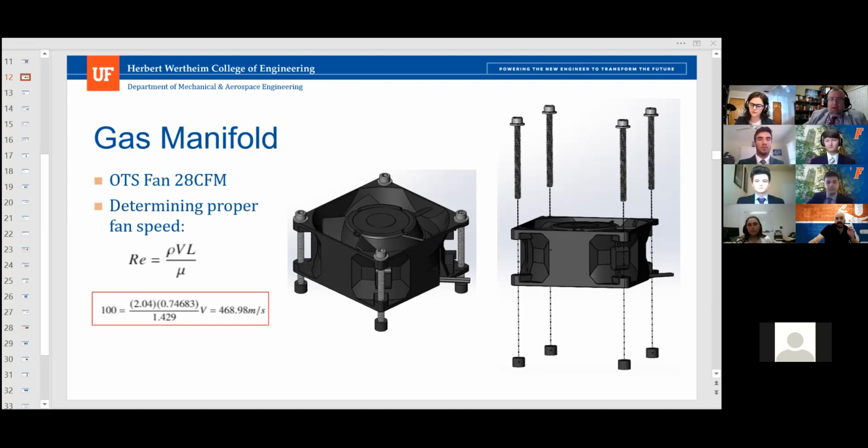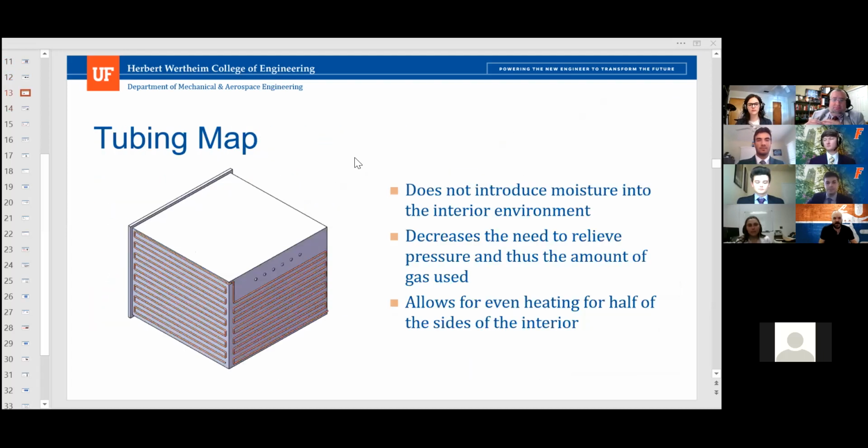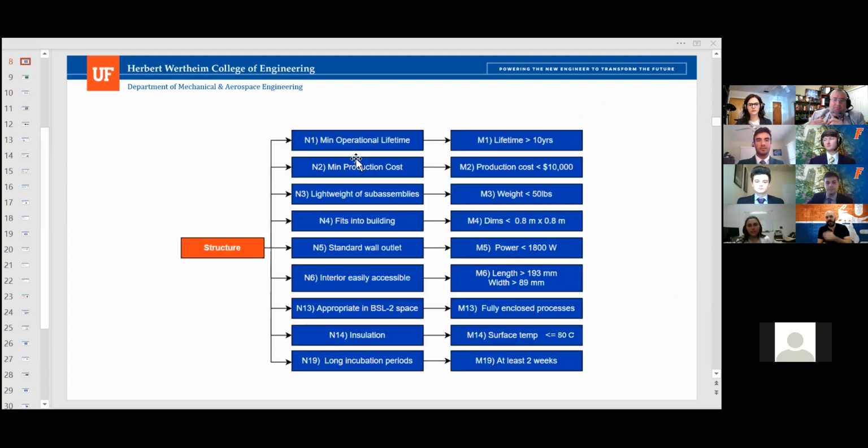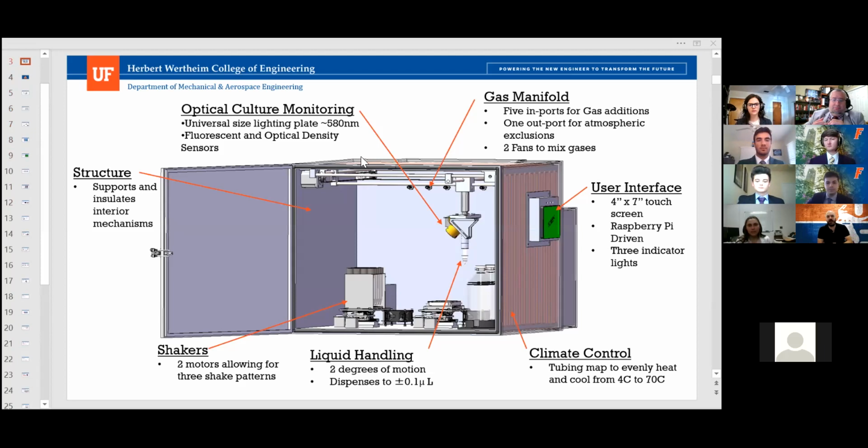And then as another point here, now that I've roasted you on one thing that caught my attention right at the beginning and I was not able to let it go: your cooling system with the pipes going through the walls. Just so everybody on the call knows this, actual incubators are water jacketed and they regulate the temperature of the entire interior of the incubator by using a mass of water that is heated and cooled appropriately. And I saw this and now I have the question, did you guys copy industrial incubators or did you come to this just by pure coincidence?